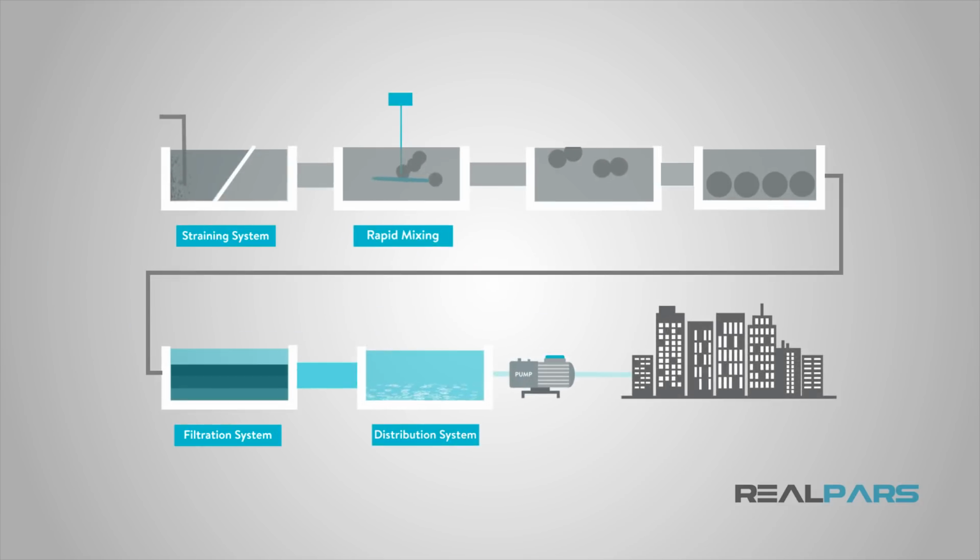With that chore out of the way, the staff will then have to stop the addition of all chemicals, as well as possibly drain the rapid mix basin. The reason for draining the basin would be that the floc would settle to the bottom of the basin and cause many problems for pumping to the next station, as well as equipment impact considerations.